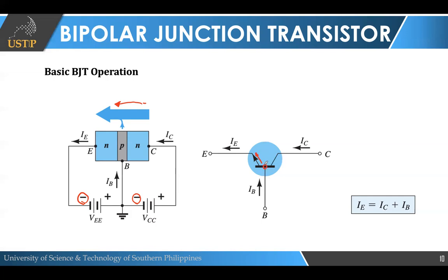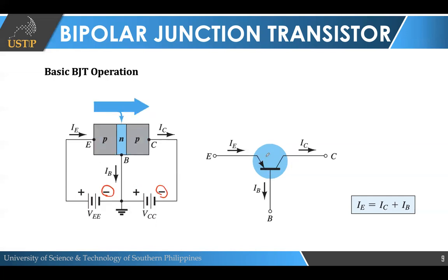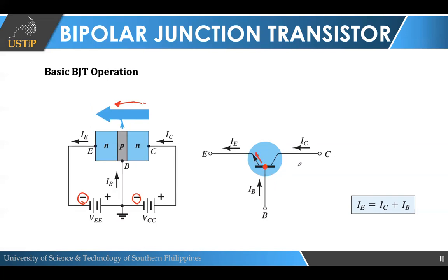So, again, think of this as your node. Earlier, at our node, the emitter current was going in, no? Then, it was distributed. Right? So, for the NPN, it goes out here. Meaning, the current in the base is going into the node. The IC is also going into the node. And then, the major current, or the largest current value, is the emitter, going out.